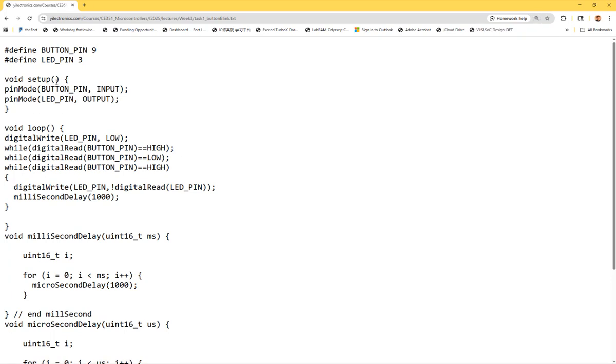Oh, there's another thing you need to know. Remember setup. You need to set up the pin mode. That's the Arduino specific thing. The pin mode, button pin. Button pin is taking in the data from the button. You press it, it's being read. So whatever signal you give through the button will be read into the Arduino as a signal, right? That's why it has to be input mode. And the LED pin is toggling the LED, so it's outputting signals, it's the output pin.